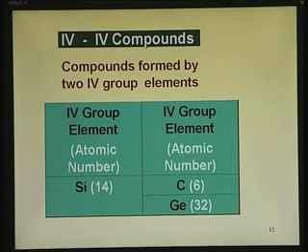Now, let us take a look at the 4 compounds. We have finished, we are still on binary: 2, 6, 3, 5 and 4, 4. Silicon, 4th group, carbon, 4th group. Silicon itself is an indirect band gap semiconductor. So, all the more if you make a compound of silicon and carbon, silicon carbide, it will be indirect band gap. If it is heavy atoms, it turns out to be direct band gap. If it is lighter, atomic number small, it turns out to be indirect.